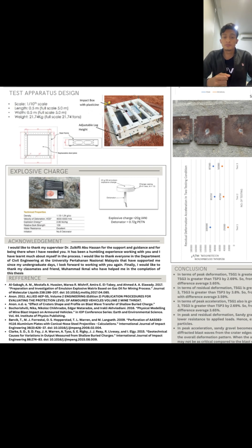The extent of the deformation can depend on factors such as the size of the explosion, the distance between the explosion and the steel plate, the thickness of the steel plate, and the strength and the ductility of the steel plate. In some cases, the steel plate may experience plastic deformation, which can lead to a permanent bending or buckling. And in more extreme cases, the plate may fracture or even disintegrate completely.